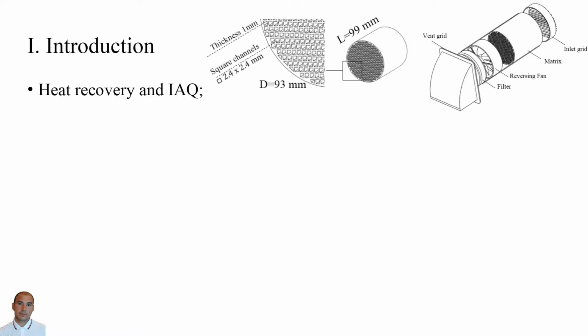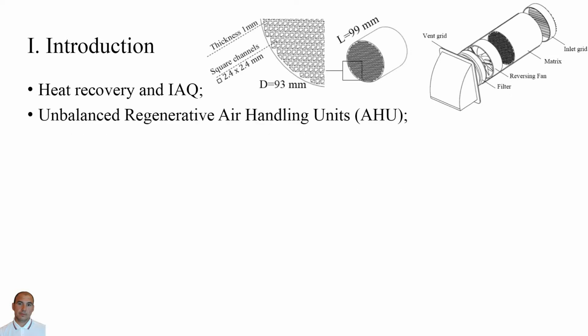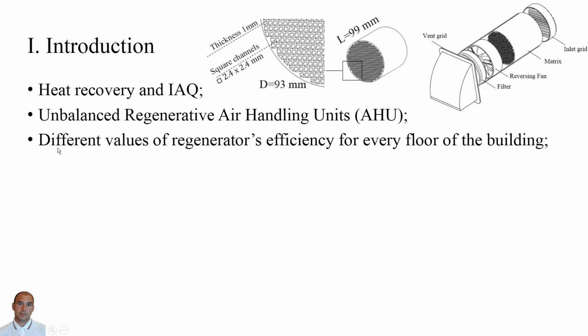Fixed regenerative heat exchangers are used in the ventilation system for heat recovery of the exhaust air from the room. Compared to industrial generators, which operate under almost constant conditions, regenerators in ventilation systems operate under variable climate conditions: variable temperature, humidity, and especially the pressure difference in the building. These variable conditions lead to an unbalanced regenerator, or in other words, to an unbalanced operating mode related to different values of